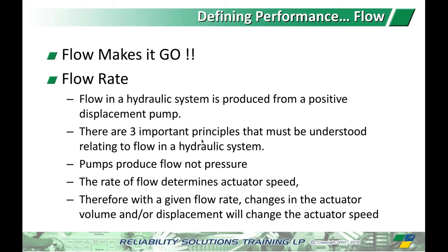And pumps produce flow. They don't produce pressure. That's a very, very important concept. What produces pressure in a hydraulic system is the back pressure from the load itself, and of course, any back pressure or pressure loss we get from valves or losses in the system, okay?